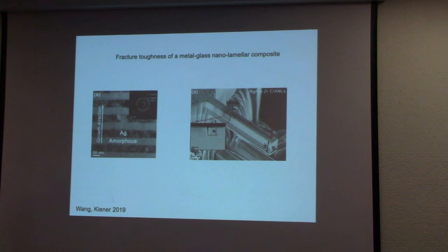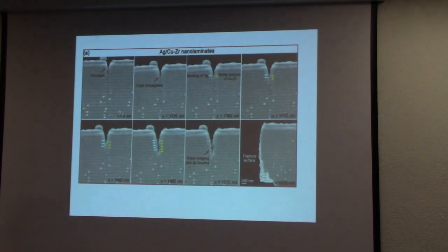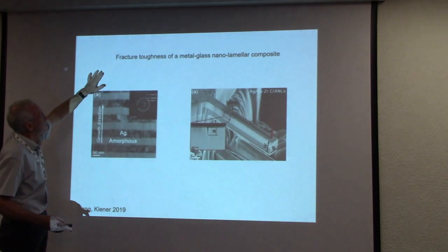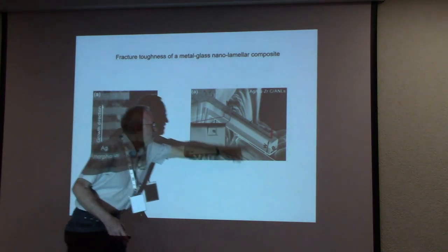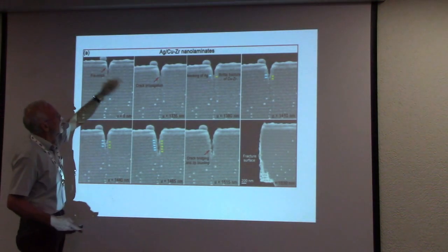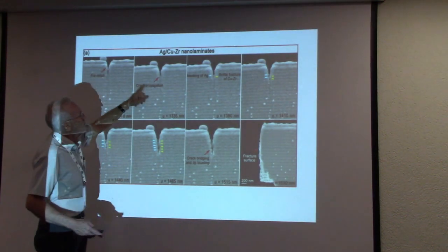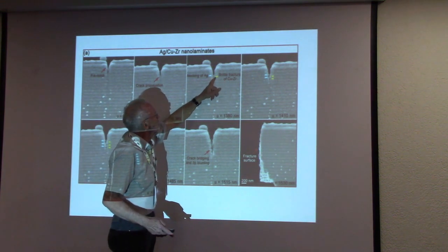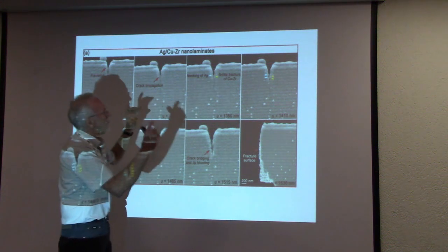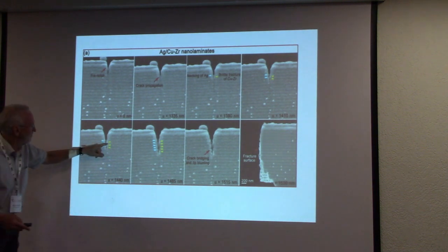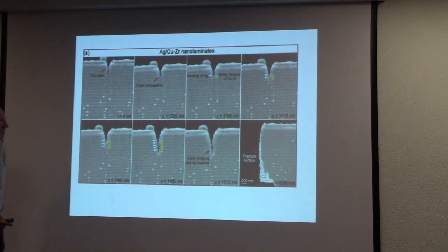Yes, and what I want to show here is that this phenomenon in the micro dimension, especially in lamellar structure, can be quite different. This was the sample. You have seen this, the macro sample, and we bend this and fracture this. This is the notch. Here we see that the first crack propagation starts because of the brittle zirconium fracture, but the metal makes at first such bridges, and finally we get some crack propagation through this film.